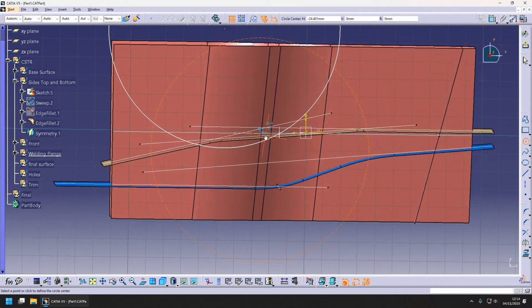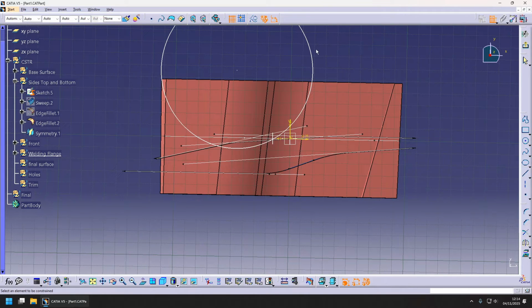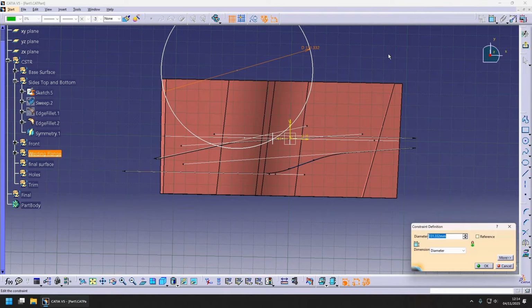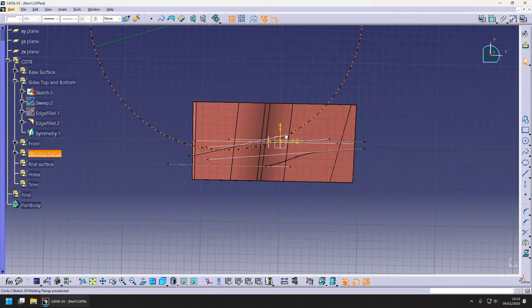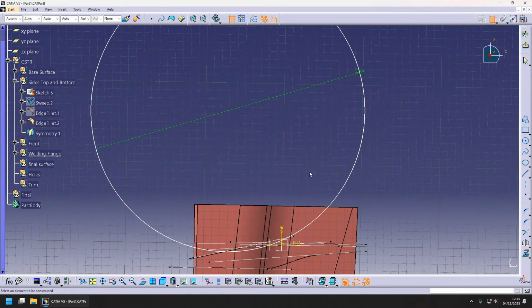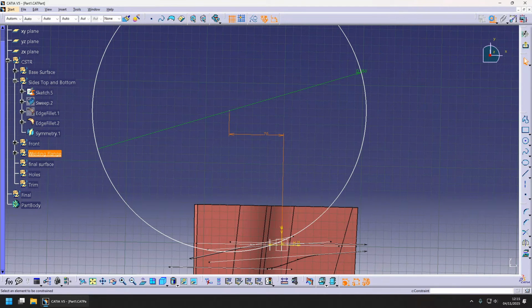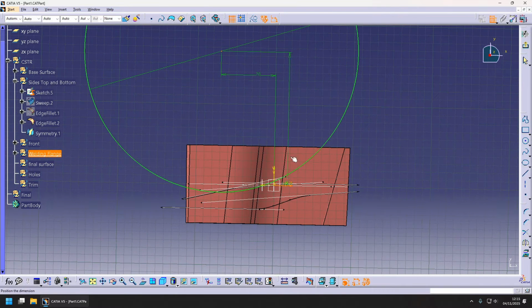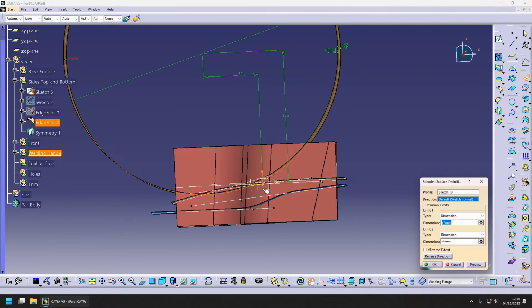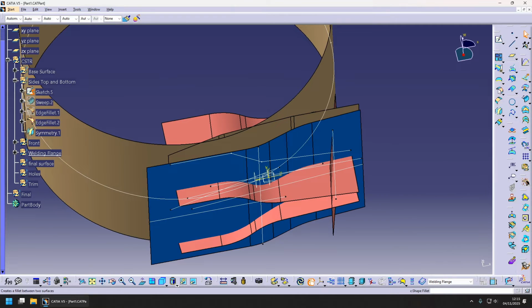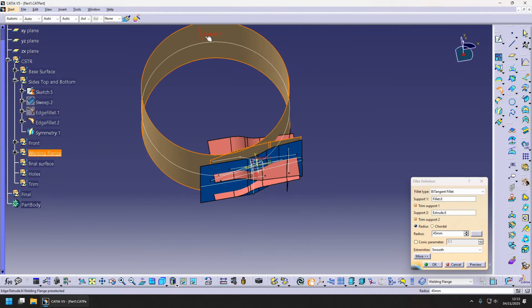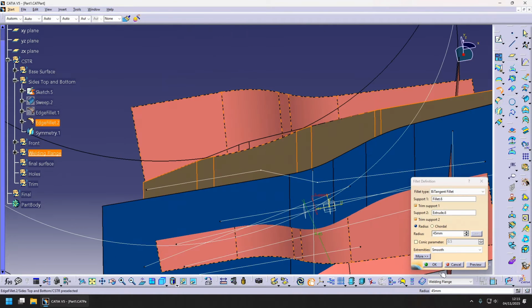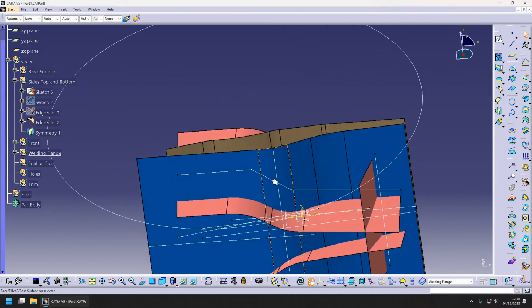We take a circle like that, and then we need to define its diameter. It's probably gonna be a little more than this. Let's say 350, something like that. 70 millimeters. In this direction, we need to constrain the center point. Every sketch needs to be constrained, and we extrude it up. Now we fillet this to the other sides. We make sure we have the correct orientation, and there we go. And now we have the welding flange.